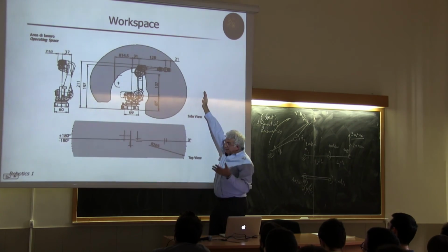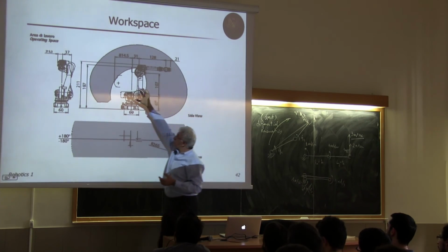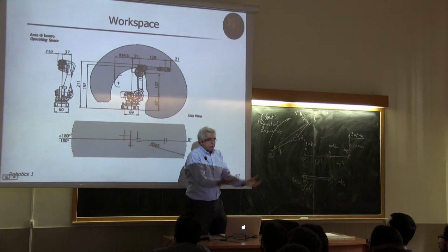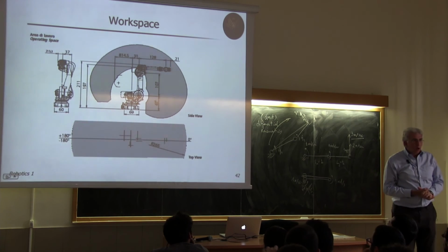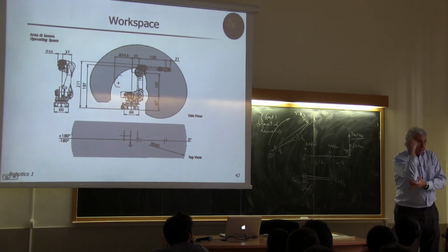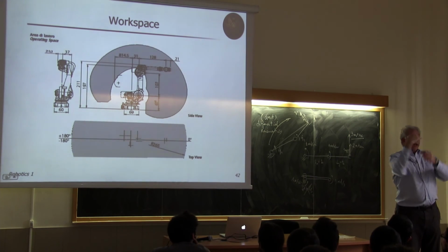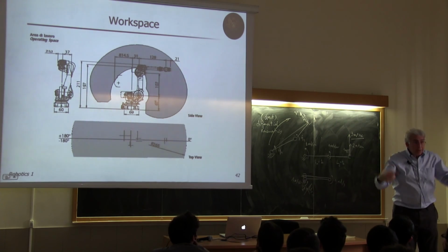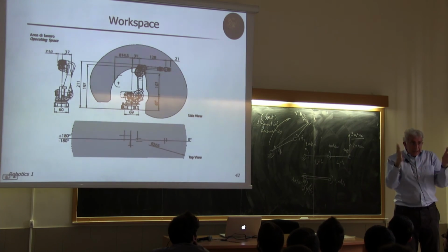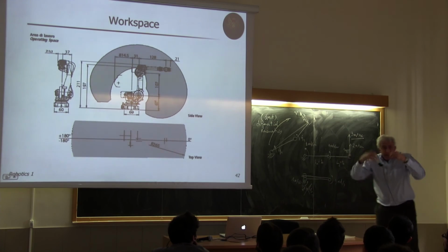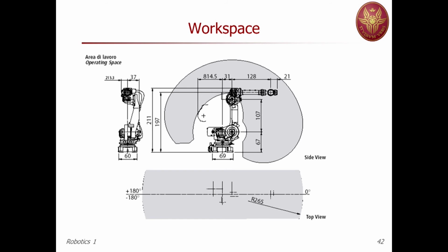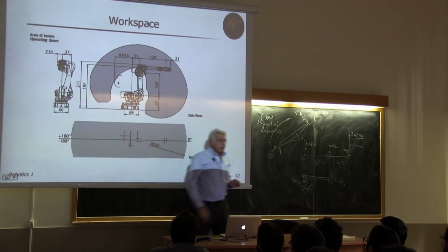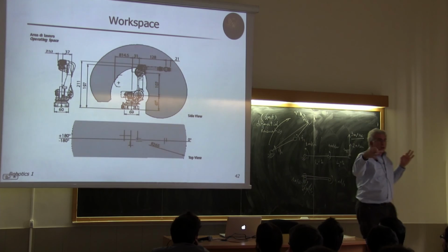But the nice thing, the critical thing, is that you will find some holes within the natural hyperbole that you have there. Okay, why do you have holes? Exactly because you have limits for the joint ranges so that you cannot access some internal points. And for the same reason, you try to eliminate mechanical stops in order not to have holes inside the workspace that you cannot reach. Now, imagine that you have to pick something here and place it there. Can you go in a straight line along a Cartesian path?